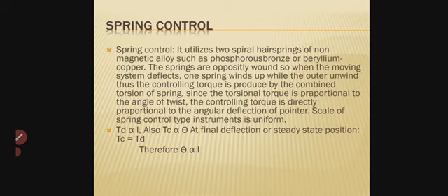This twist in the spring provides the controlling torque. As we have discussed, the controlling torque is always opposite to the deflecting torque, so the spring provides the controlling torque.